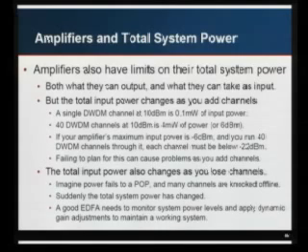So the amplifiers actually have a minimum amount of power and a maximum amount of power that they can take, because if you start with too strong a signal and you try to amplify it, number one, there's a limit to how much signal you can put across the fiber before you start causing more nonlinear interactions. And number two, there's a limit to the engineering of the amplifier, right? So you want to start out with a signal that's low but not too low, and then amplify it to a signal that's high. You don't want to start out with a really high signal.